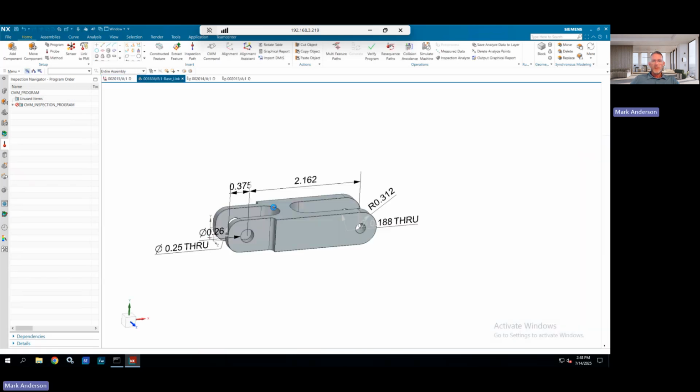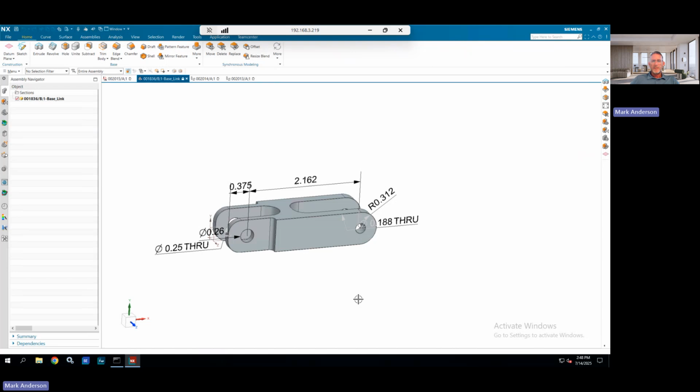It allows us to auto-generate the draft, and then we do very little work there. But then it also allows us to automate our programming off of it in manufacturing. That's how we can not just drill a 260 hole, we can do a fine bore or a surface finish. We can bake them into the feature-based manufacturing.